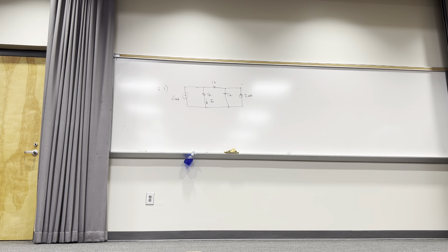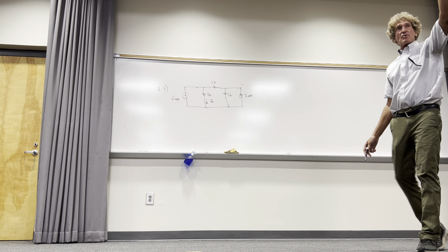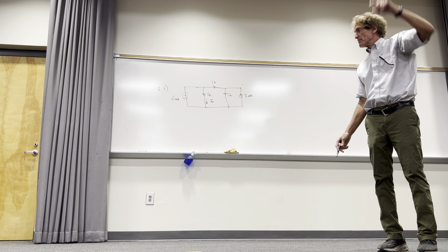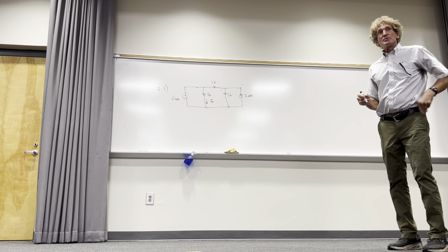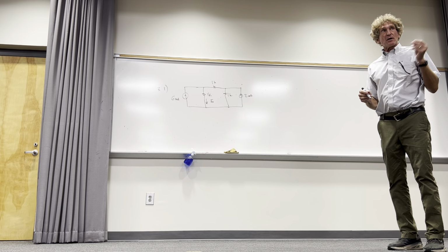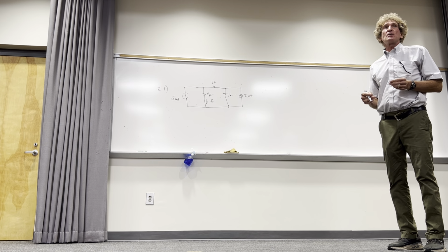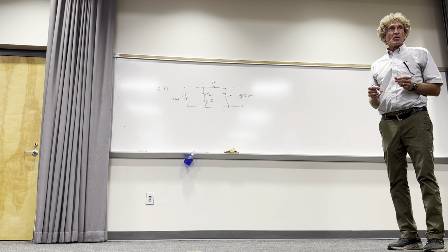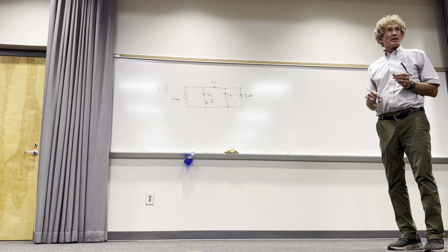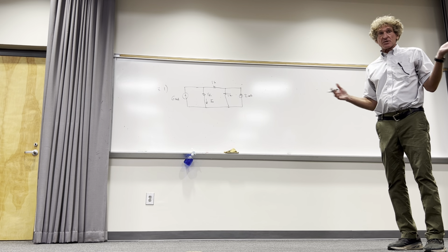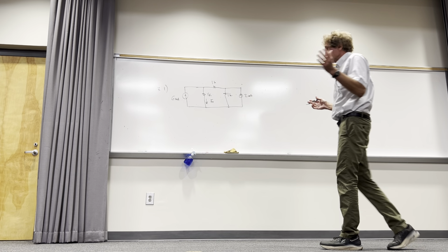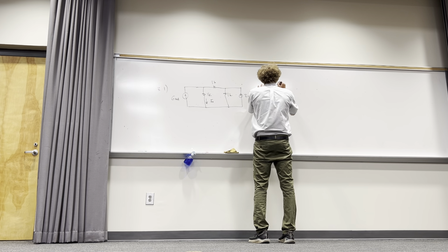We're going to use Thevenin for this one. First, can everybody see it in the back? That's the most important thing that I've got to ask. Far back? Okay. So, in this problem, we're going to use Thevenin's analysis. Now, hear me. The very first thing you do is identify the component that you want either the voltage or the current through. In this case, what is it? The 1K resistor. Does everybody see this? I'm just asking for a confirmation you can read it. So first step, RL is equal to 1K.